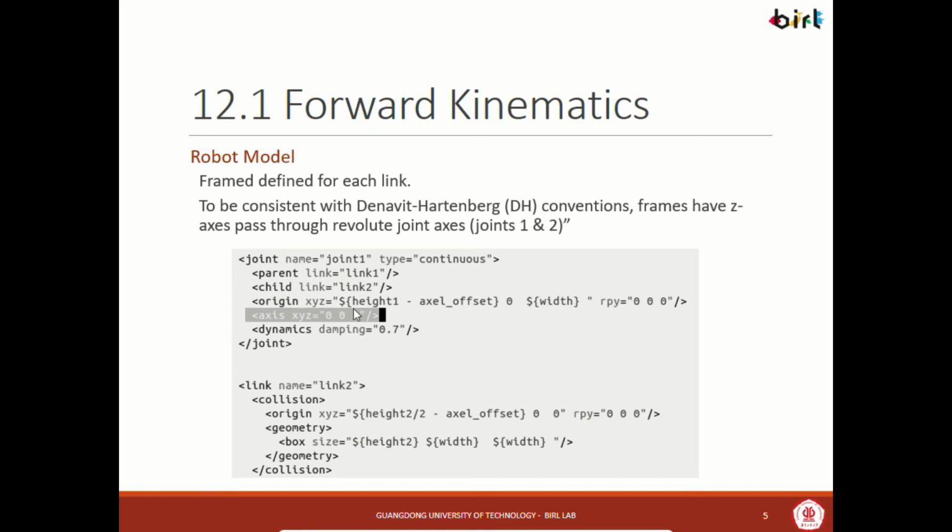Okay, so this is setting a URDF file to follow the DH parameter conventions. This is not typically done. But this is a way that our book is helping us to understand how to do DH for kinematic computation if we want to use ROS. So you would have to do something like this.